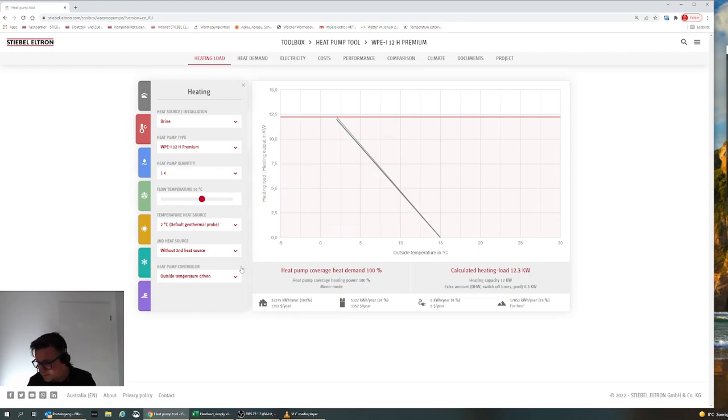But there's a big question mark. The efficiency and the power capacity of these geothermal machines has a big relation to the source temperature. European climate is a little bit colder, Northern European climate. So the geothermal probe that I have in my house gives me 6 to 8 degrees during the year.